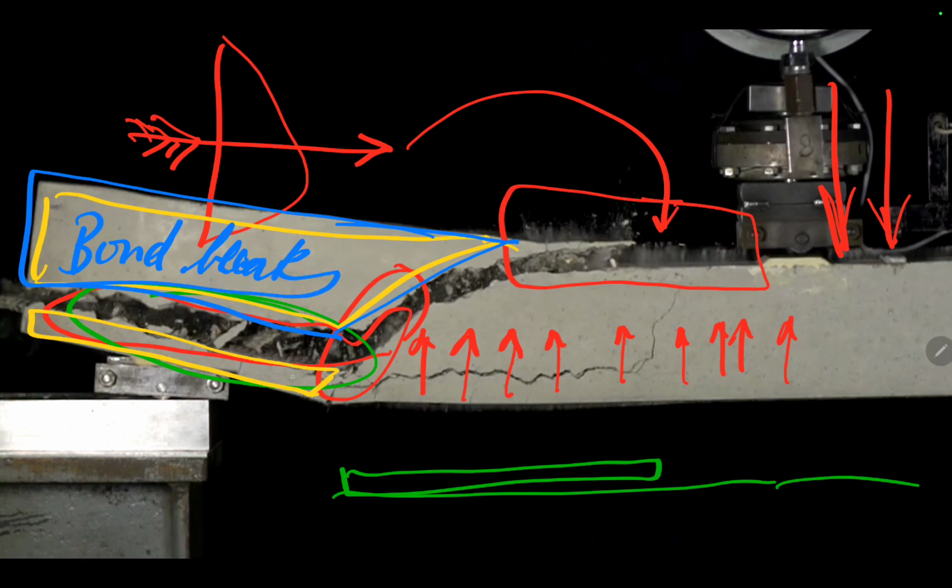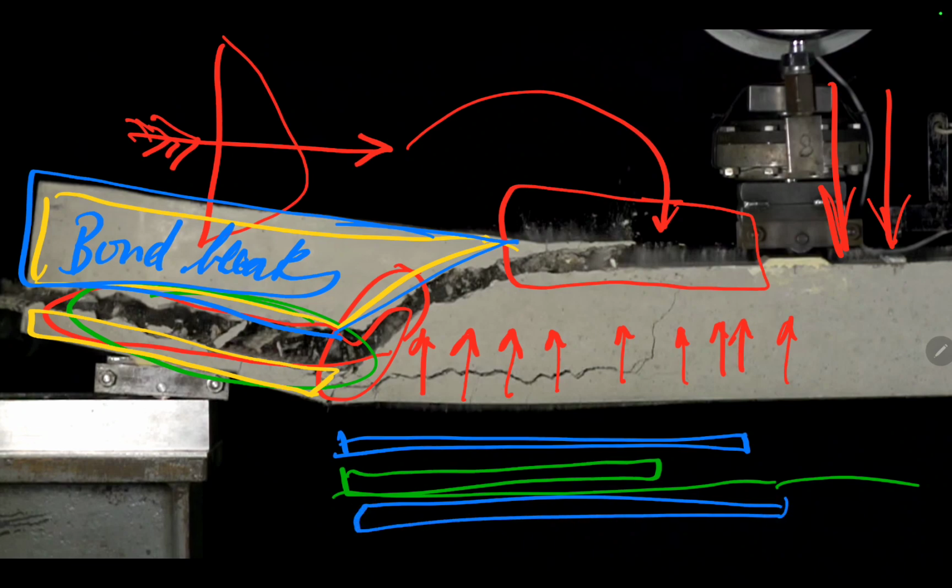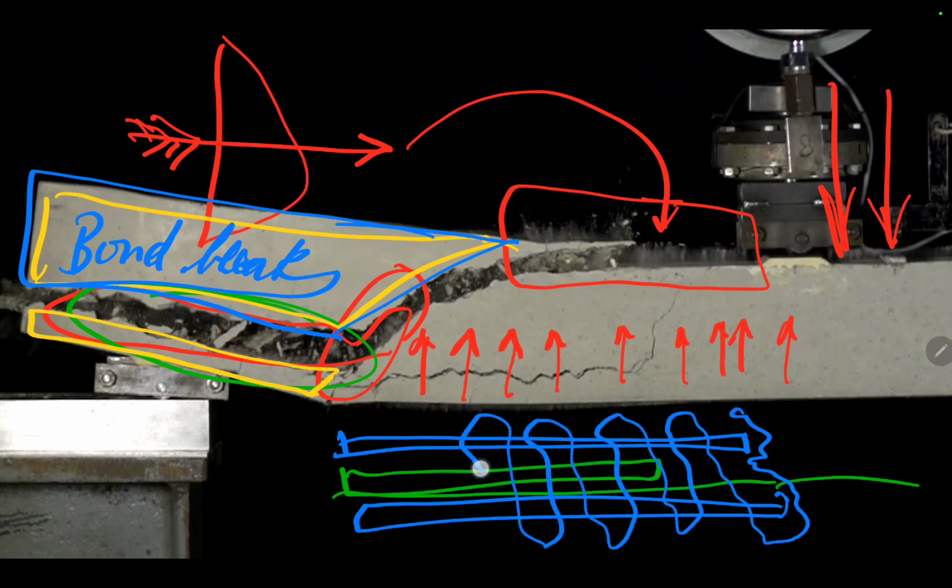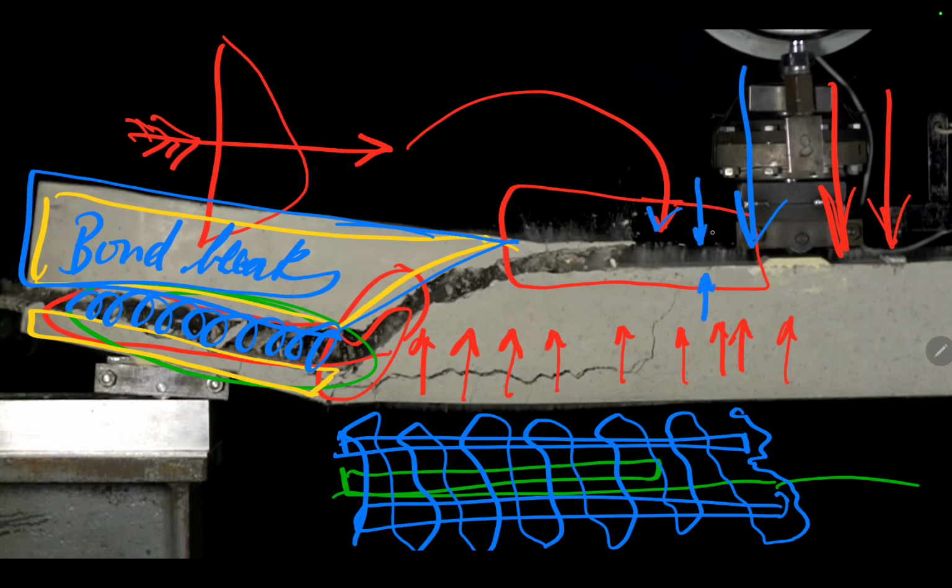Right here, this section breaks apart from the rebar itself, creating a plane, a shear plane. Say there's two bars in there, we're looking at the top view, if you will, and the reinforcements there. But it's got to hold the concrete together. I mean, the concrete's got to bond around it. And when that force is applied, it breaks apart. That kinetic energy is there, and you get your boomerang, your arrow, your direction, your released energy, your kinetic energy is shown in this direction with these little fibers. Let me get you now the bridge.